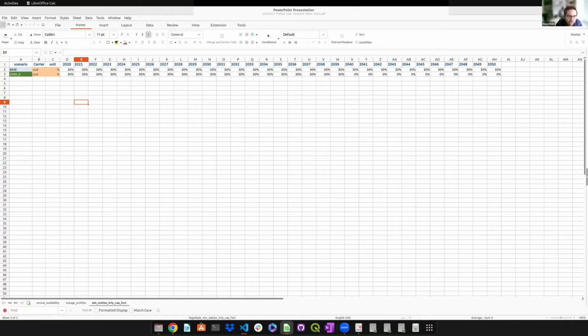But it's not possible to do both capacity expansion and unit commitment in the same model, because as part of the maths, you have a status variable that gets multiplied by an installed capacity variable. So both of those can't be unknowns in terms of keeping the model linear.